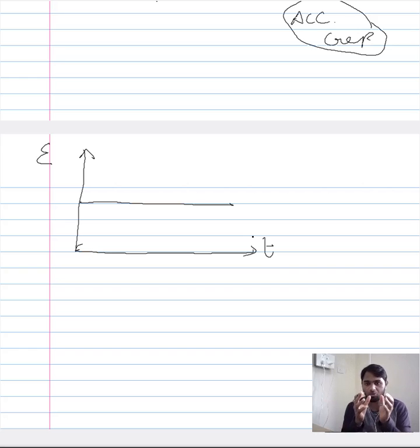When I focus on one section, I just have to consider the theoretical reason why such a behavior is exhibited. Now, when I section the overall creep curve into different regions, study the theoretical reason for each region and ultimately combine it into an overall creep curve, this approach is referred to as the phenomenological approach.